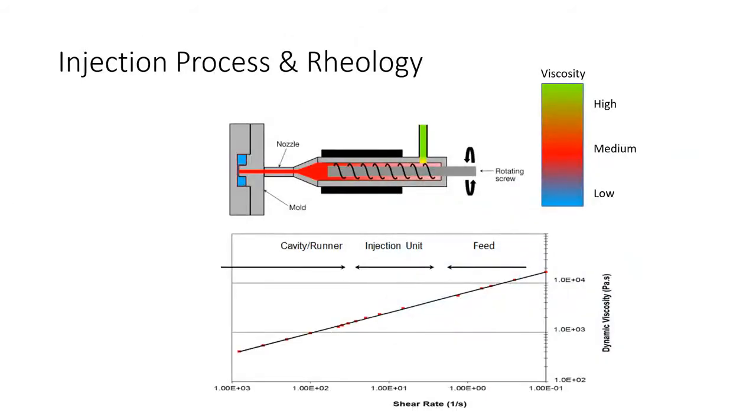Looking at that, and understanding this concept of high viscosity rubber going through the flow process into the runner system and into the cavities, we see a change in viscosity. Typically we see viscosities that are quite high. Note this is a log graph. It's a little backwards because I plotted it this way; we usually see this turned around.